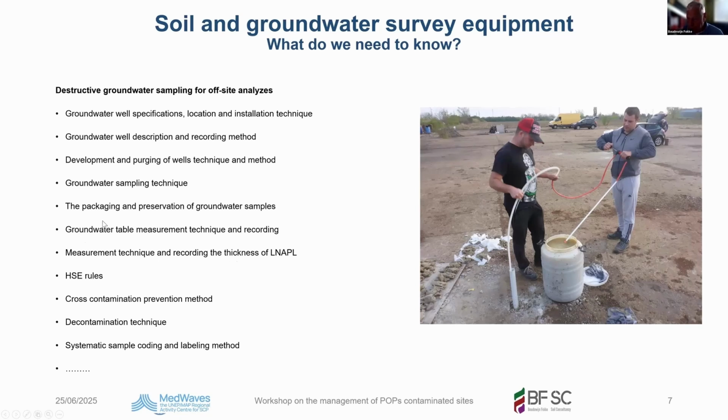Then the next one is the packaging. What do I use? Bottles, glass bottles, plastic bottles, PE bottles. And this gets important nowadays, especially when you have a groundwater contamination with PFAS, because many tubings and pumps may contain PFAS or PFOS, and then you get cross-contamination.